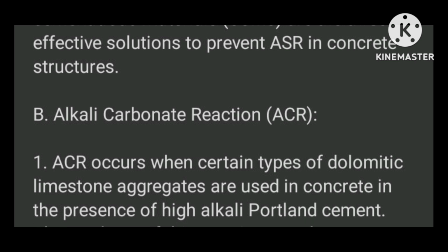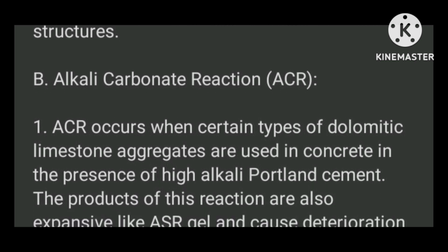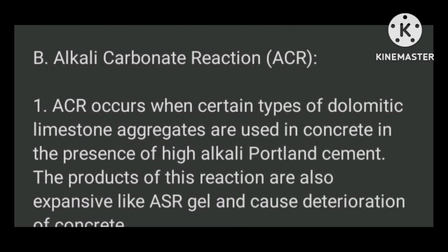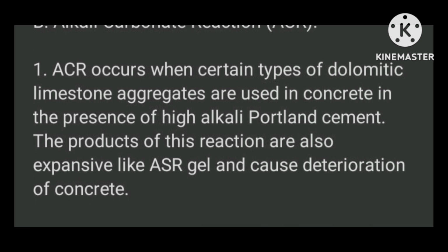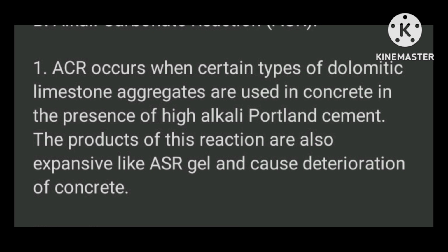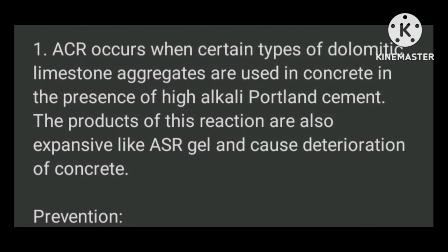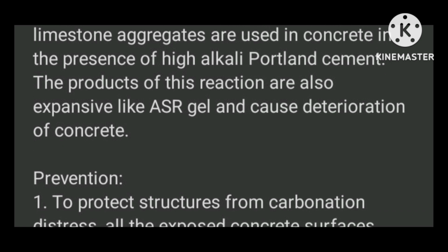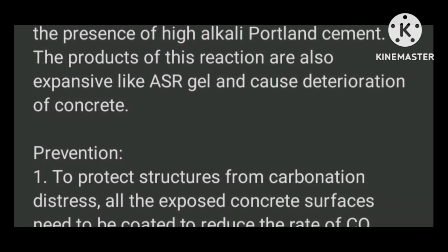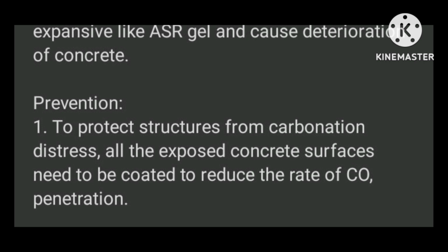B. Alkali carbonate reaction, ACR. First, ACR occurs when certain types of dolomitic limestone aggregates are used in concrete in the presence of high alkali Portland cement. The products of this reaction are also expansive like ASR gel and cause deterioration of concrete.